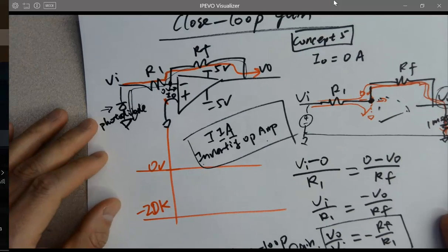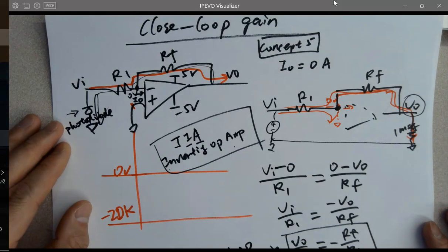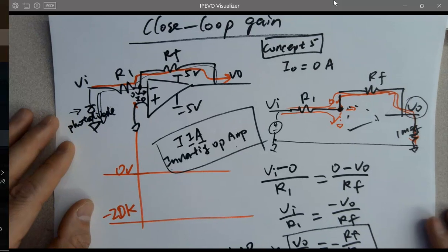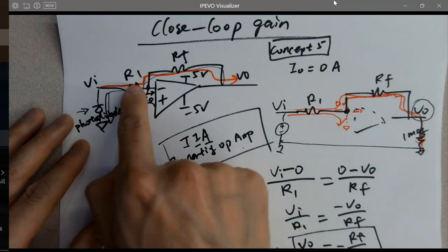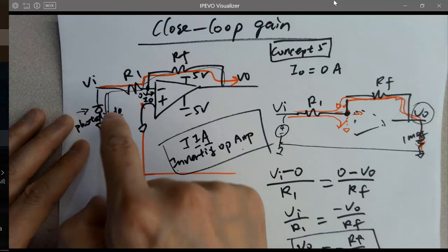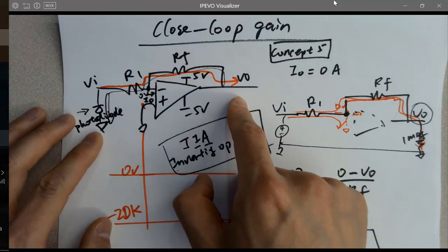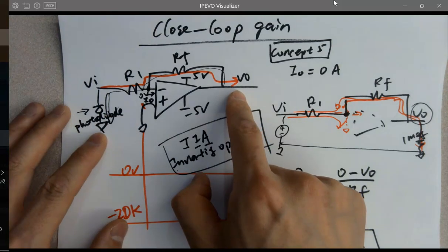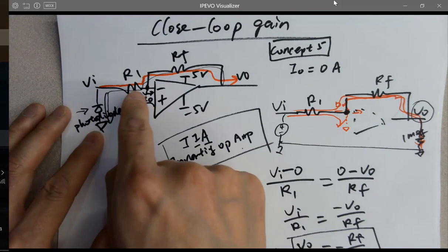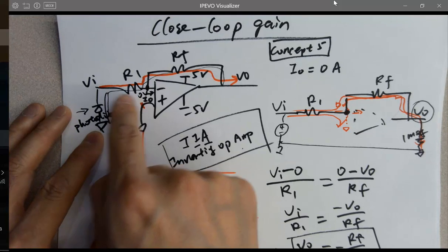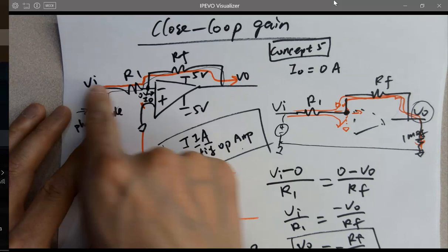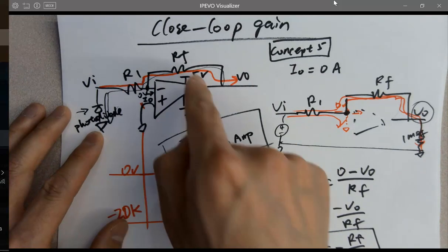So can you say that we are using the voltage inside to gain the voltage instead of dropping the voltage? No. This inverting op-amp converts current into a voltage. This is another point that confuses people. You have a voltage input, so why are you converting a current? Actually the voltage is being converted into current because you have a resistor here. So the voltage is already being converted into a current, and it's amplifying that current by RF over R1 to a V out.